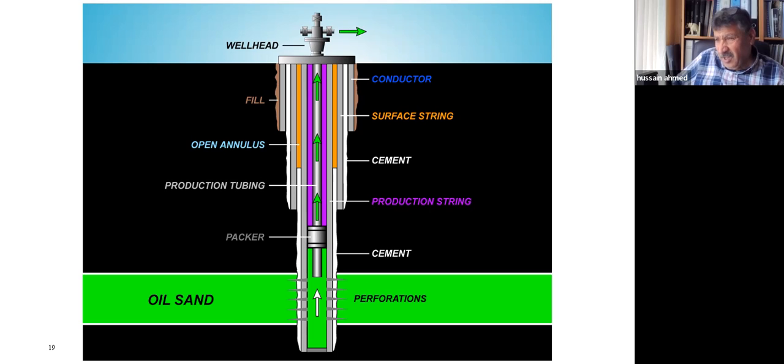So a well integrity engineer's job is how to protect the well from getting damaged, how to protect the well from getting intervened with by other fluid from the pay zone or from the surrounding formation. So they look into the cement, any cracks in the cement and why. The casing is a barrier, they call them barriers. The cement, the casing, the formation, the cap rock, the packer, the production tubing, these are barriers.